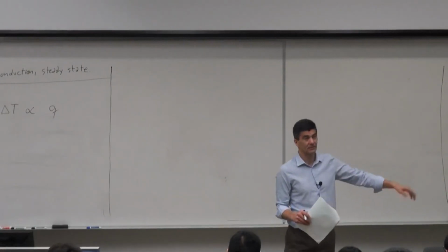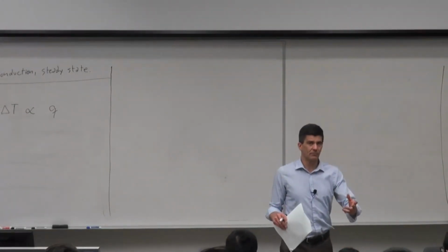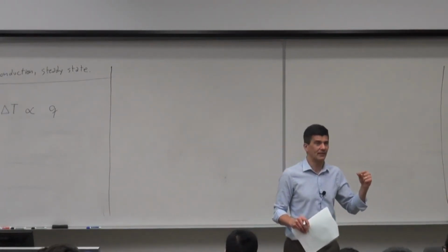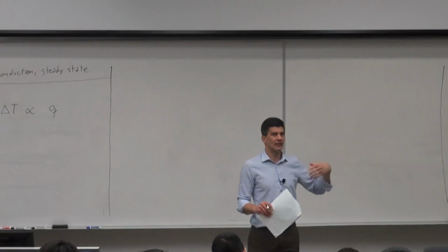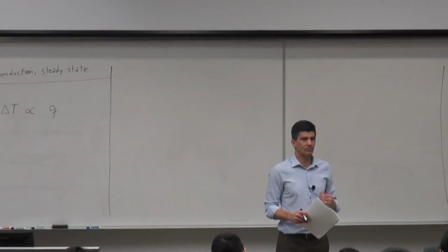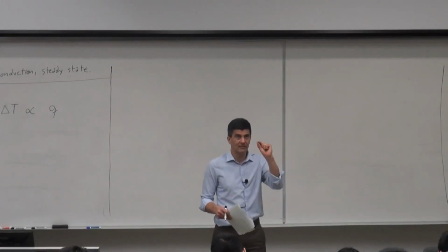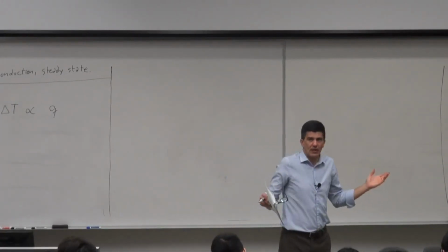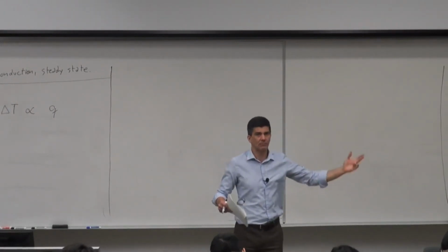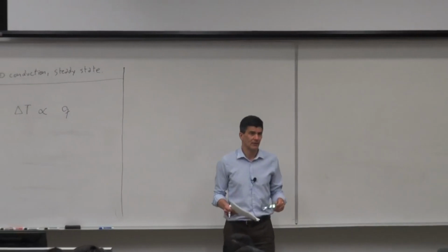In reality, everything that seems flat is something round, but at this distance it looks pretty flat to me. From the point of view of heat transfer, if the wall is thin enough, it's going to look pretty flat to the energy that is being transferred. So this idealization of a plane wall is actually pretty awesome, because you can do not only cylinders and spheres, as long as the thickness is thin, but you can also do crazy shapes. Who cares, as long as it is thin compared to the other dimensions. So very, very powerful. And we did this with a very trivial equation.